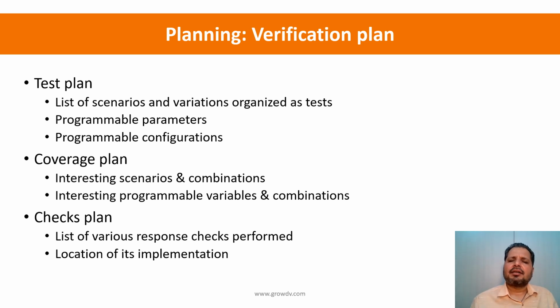And along with that, there could be programmable configuration. What it means is that you could have, let's say, your mobile phone, and it could have an OTG USB port, right? And OTG means that a port could act both as a host as well as a device. So now if I were to implement a simple data transfer test, then I have to run that test in both the modes, with the mobile port acting as host as well as the mobile port acting as a device.